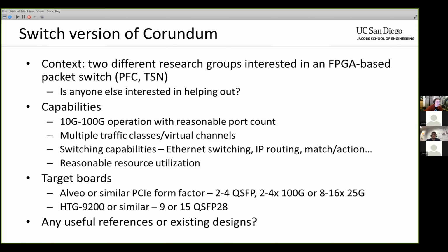So I'm almost thinking maybe there has to be something hierarchical here. For example, you might have a module that can handle a single 100 gig port and does this kind of routing. Or, if you're doing 25 gig, maybe you can have 4 or maybe 8. Because the packet rate is lower, you have some more cycles perhaps to do matching, and you can share resources more effectively, something like that.